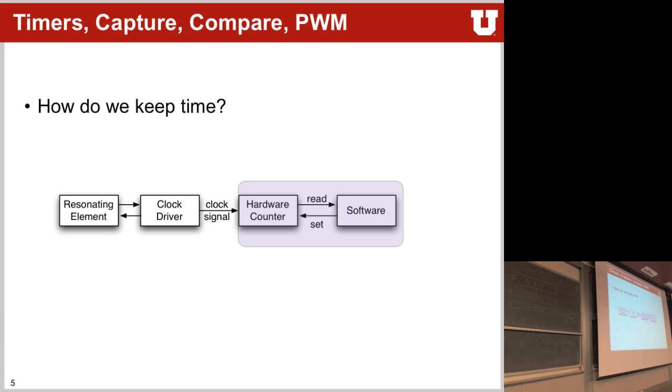Okay? So now how can you generate a signal that has 80% as its duty cycle? Just take whatever is 80% of what's in CCR0. Correct. So 0.8 times 2 to the 14. Can somebody calculate that?